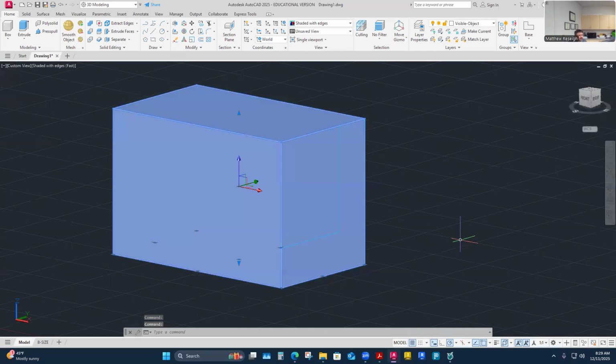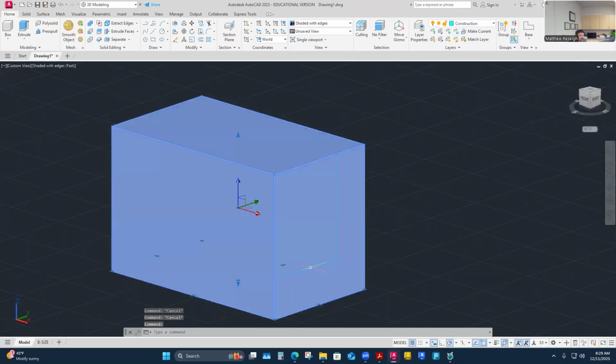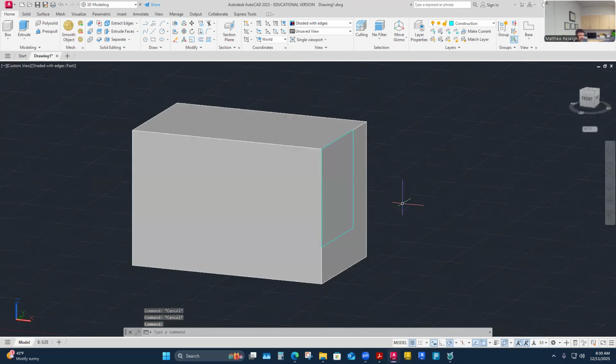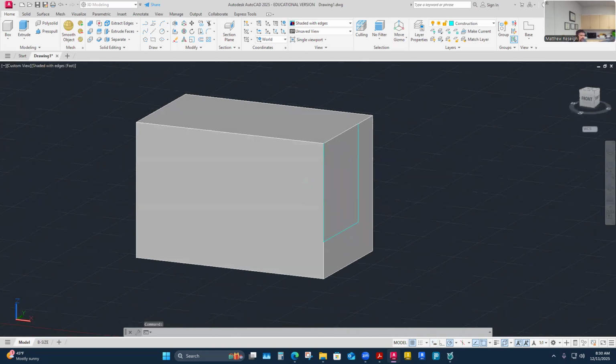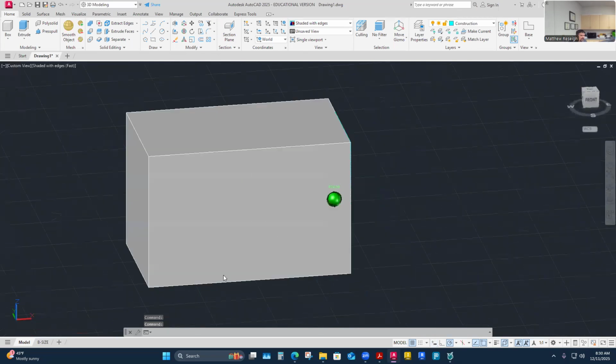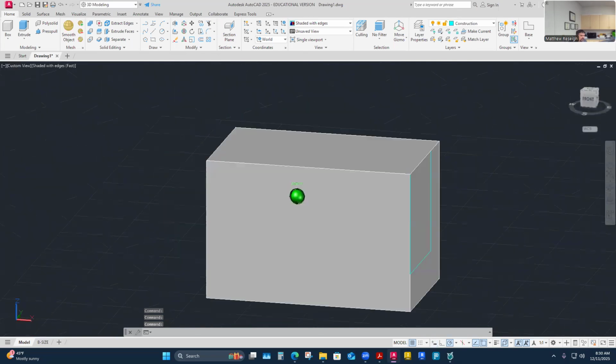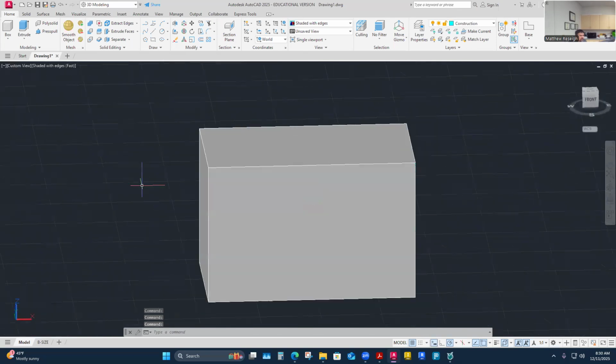So, I've done a polyline. This shape should be a closed polygon. I'm going to turn this on. This is my sketch to cut in this way to the gusset. I want to cut this way as well, so I'm going to mirror this sketch across this. Mirror works similar to how it does in 2D, only it's a 3D mirror. So it likes 3 points instead of just two. A 2D mirror just needs 2 points and an axis. 3D just needs 3 points. So let's do that. I don't think I've done that yet.